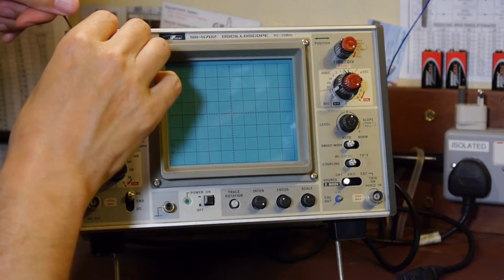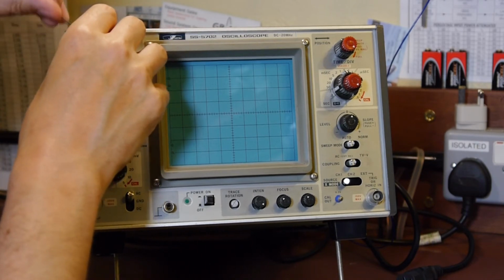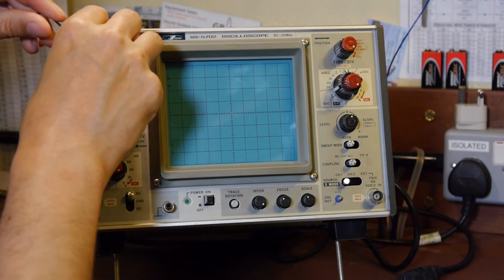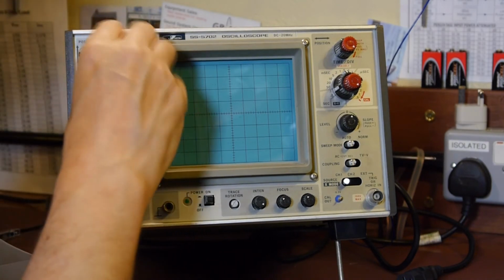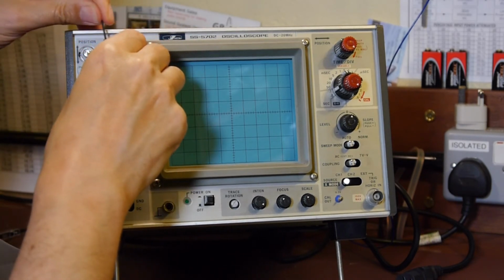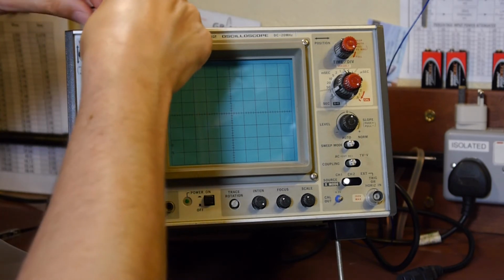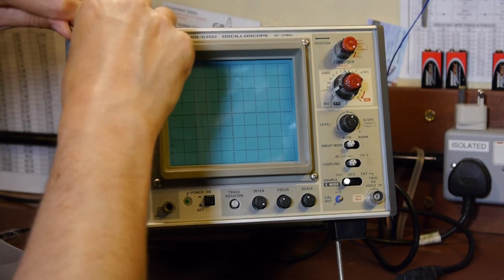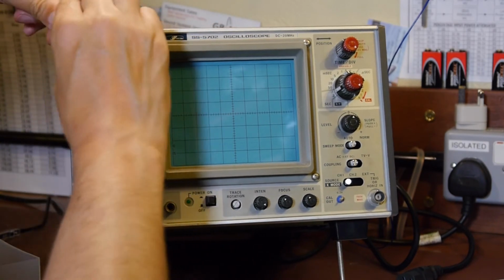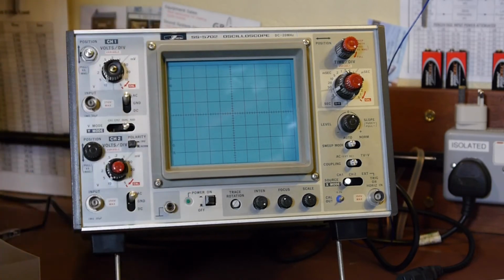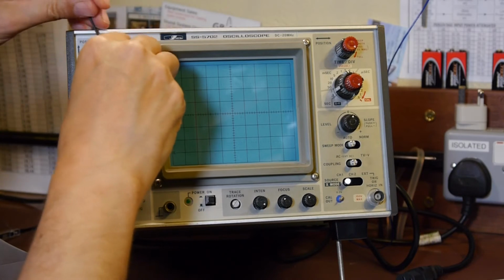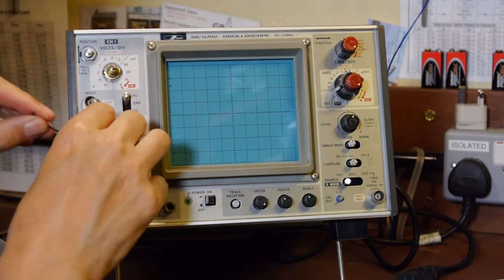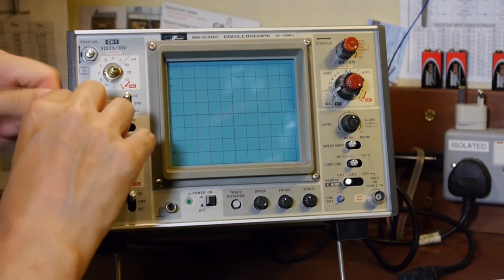It just seems funny that we've had two of these scopes, and we've had very similar problems in that it was these switches that were broken on both of them. One of them, it was the fingers on the switch contacts that were broken, and on this one it was a physical PCB board that's cracked. But I guess maybe these are typical faults that scopes suffer, and if there is some mechanical movement allowed in the actual switch itself, that's going to transfer through. It's a shame though, this scope's in really good condition, so it is a shame that it's got a broken switch wafer.